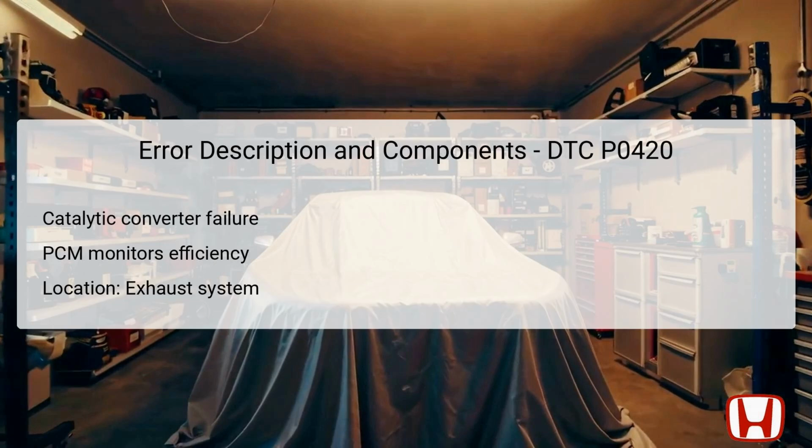The DTC P0420 specifically points to a decrease in the efficiency of the catalytic converter. The catalytic converter is vital for minimizing harmful emissions by converting them into less harmful substances before they exit the exhaust system. Positioned between the exhaust manifold and the muffler, it plays a significant role in the vehicle's emission control system. The Powertrain Control Module, PCM, continuously monitors the performance of the catalytic converter through input from upstream and downstream oxygen sensors.